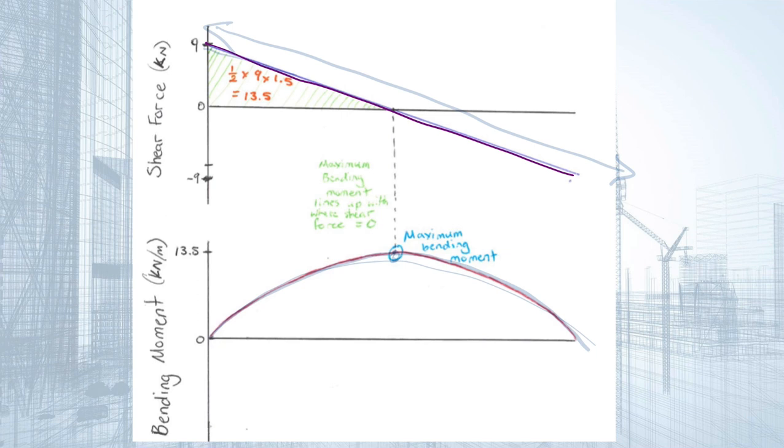So you don't actually have to do calculations involving this, but you have to recognize these facts, that in a bending moment diagram, it's going to end up as a curve with the maximum bending moment at the peak of that curve, and the shear force is going to be a line going diagonally through some sort of point. That'll often come up in multiple choice.